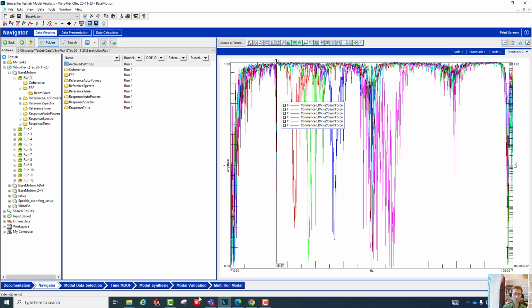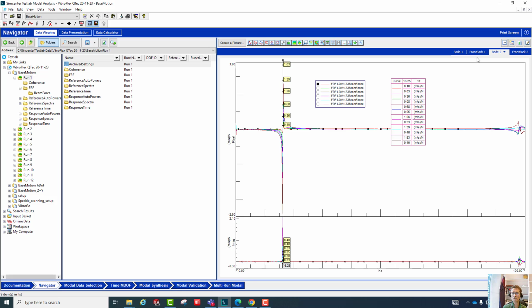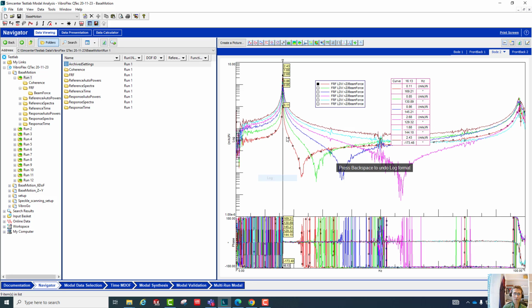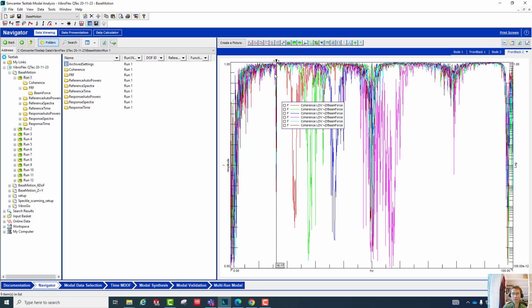So even though the accelerometer still makes a measurement of sorts, and we can see the resonant frequencies in the FRFs, the extra noise is coming about as a result of the fact that the signal conditioning was poor. The extra noise on the coherence function, for example, in this area, and particularly at that resonant frequency, would have been avoided if we'd had the proper IEPE signal conditioning. So we will need to make those measurements again.